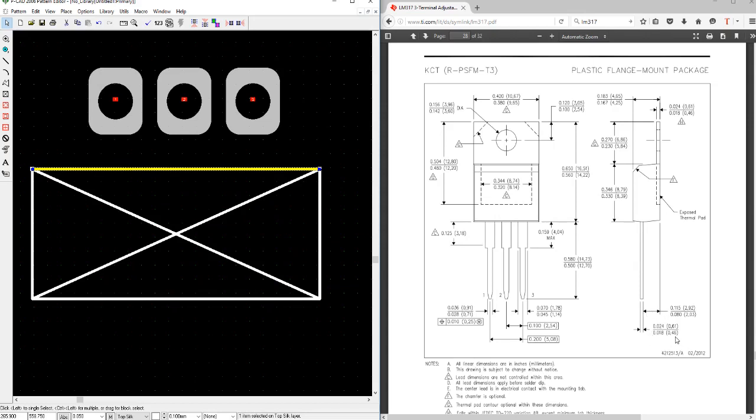Now have a look. You first need to determine the nominal distance. So again, you take the 0.61, you subtract the 0.46 from it, you divide it by 2, you add it to the 0.46. Then you get a distance of 0.405. So that is the distance that you are going to be working with. Then you also need to take the 2.03 minus the 2.92, divide that by 2, add it to the 2.03, you get 2.69. So you take that nominal distance plus half of that thickness, and that gives you then a distance of 2.89 millimeters that we need to be from the edge to the center of this pin. So we are going to be working on 2.89.